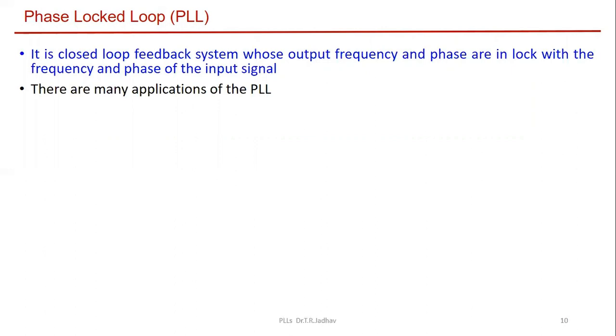There are various applications of PLL that you will find in the literature. Few of the applications I have listed here. One of the applications which is very popular is frequency multiplication and division. Here we obtain the output frequency as a multiple of input frequency. For example, from 1 kilohertz, if you have to generate 5 kilohertz, that means 5 times 1 kilohertz, that is possible, and that application is called multiplication. So frequency multiplication and frequency division is possible with the help of PLL.